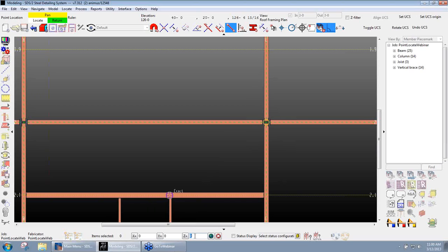to my offset controls at the bottom, type in there -2.5. Now when I locate my point there, snap to that point, it offsets where I'm snapping to, and now notice the XYZ feedback at the top gives me 126-7. Looking up here, okay, 126-7. I can come up 2.5. If I type in a positive 2.5, I now have 127-0.